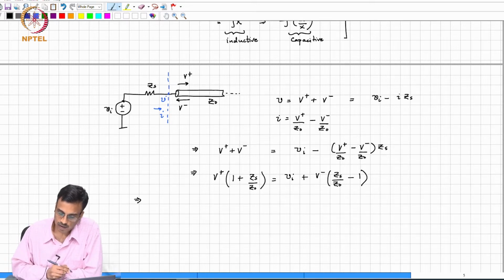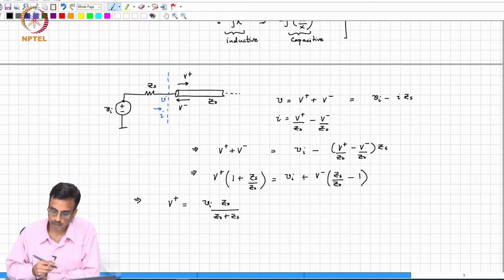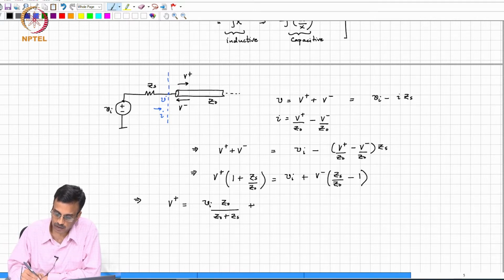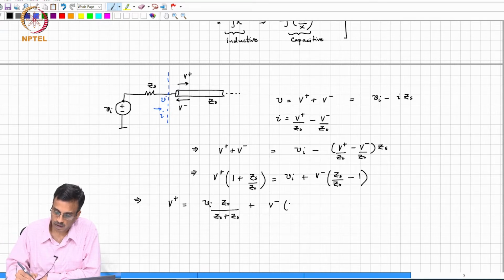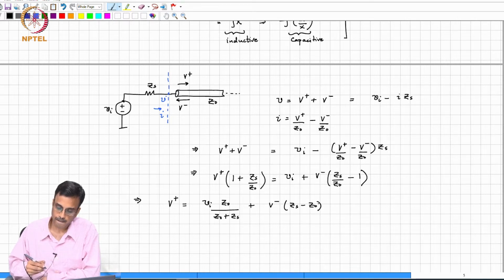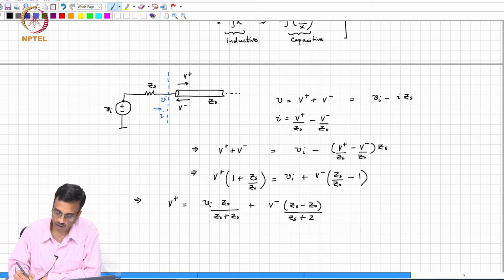Which means that V plus is nothing but Vi times Z naught by Z naught plus Zs, plus V minus times Zs minus Z naught by Zs plus Z naught.